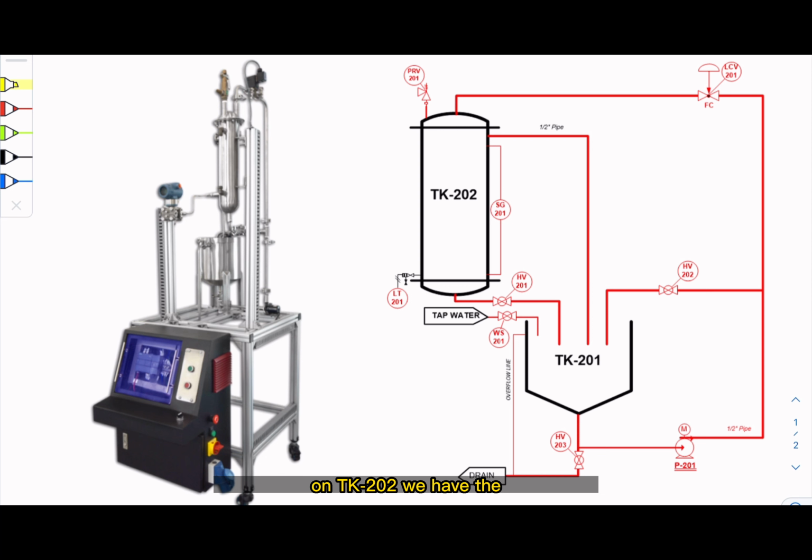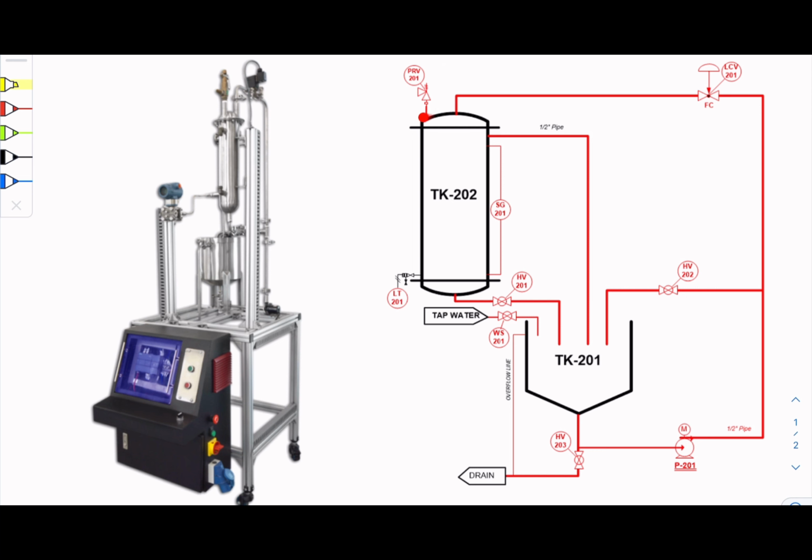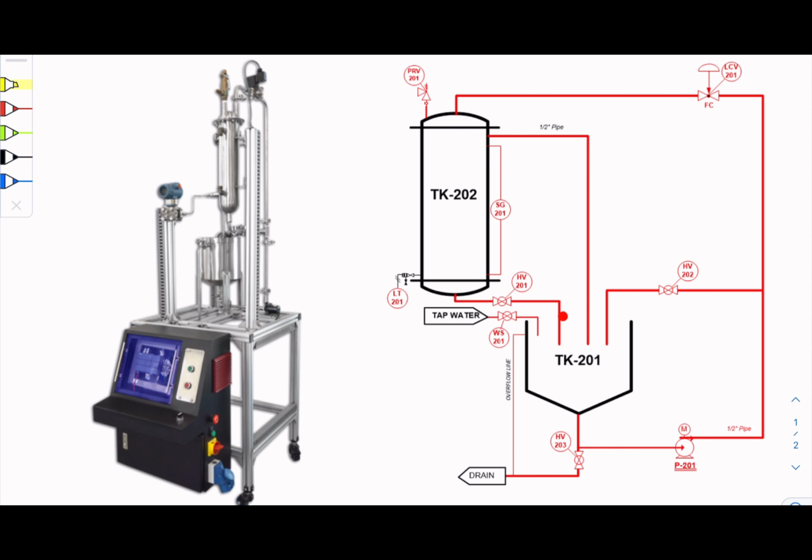On TK202, we have the side glass, which is the visual indicator, and then we have the level transmitter. Apart from that, we have a pressure relief valve. At the bottom of the tank TK202, we have a hand valve, which is just a manual valve, and it comes back to TK201.